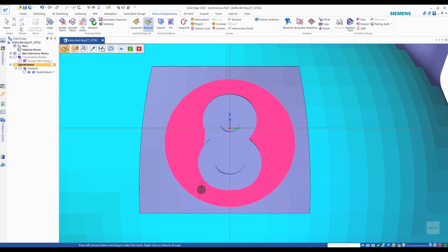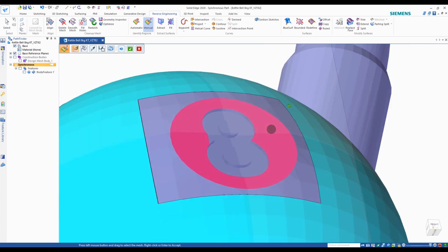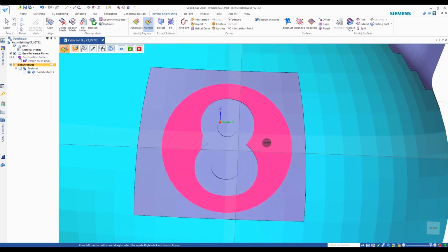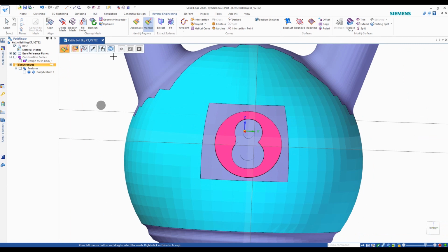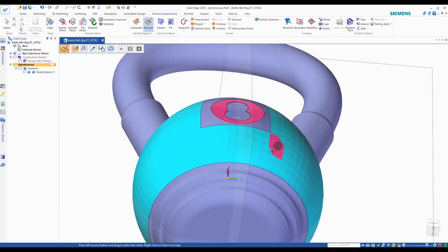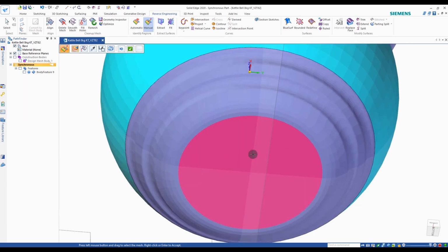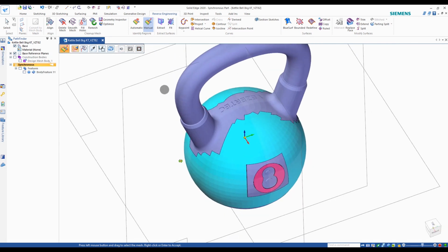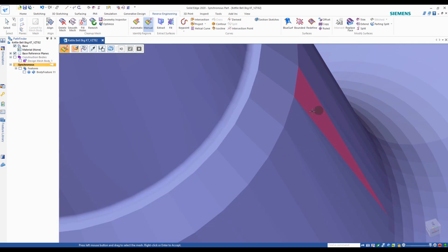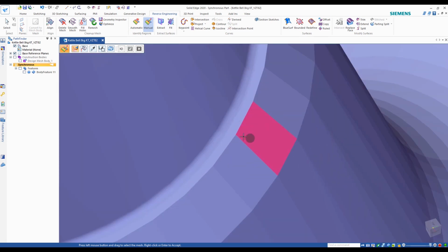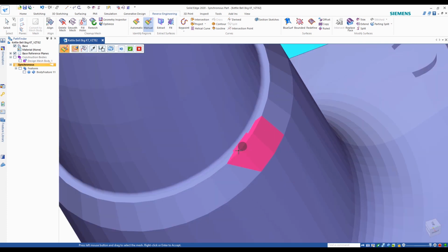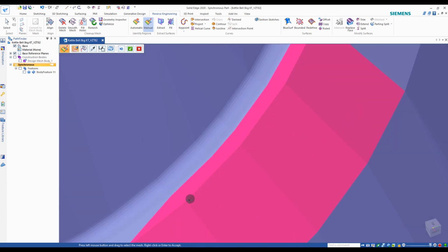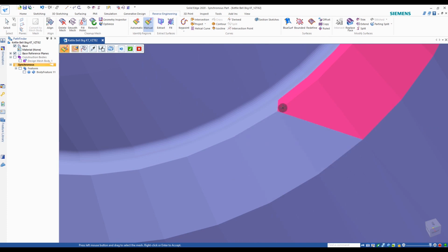And if you need to get more fine areas or smaller areas, the way to do that is you just zoom in and your brush becomes finer. And then if you need to do more coarse areas, just zoom out and your brush obviously becomes bigger. I capture the bottom, a flat plane as well. And there's also a little flat plane here just along the edge that I want to capture. I'm going over the edge and taking the chamfered surface as well, just to make sure I don't get those mini rounds in there.